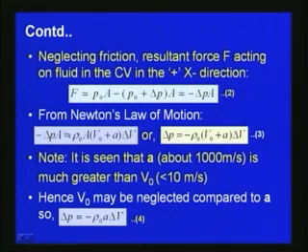So, net resultant force is equal to rate of change of momentum, and we get the change in pressure delta P is equal to minus rho 0 into (V0 plus A into delta V), as in equation number 3. So, we get the pressure change delta P by equation number 3.